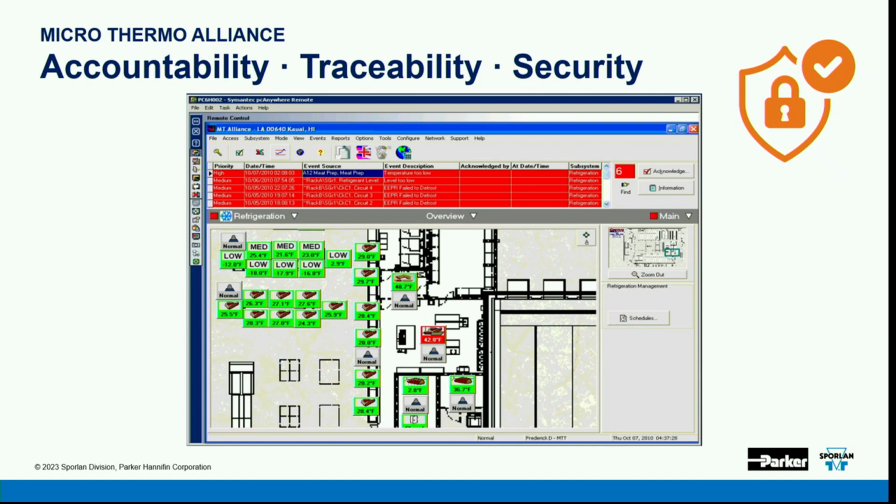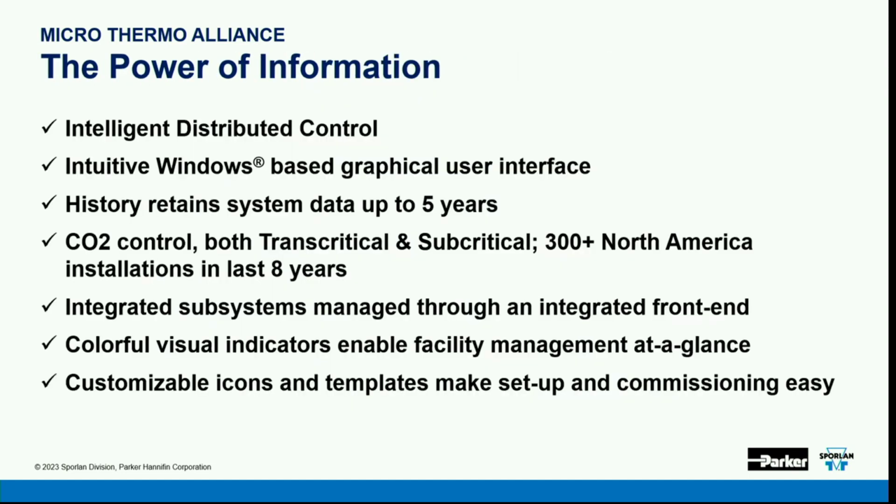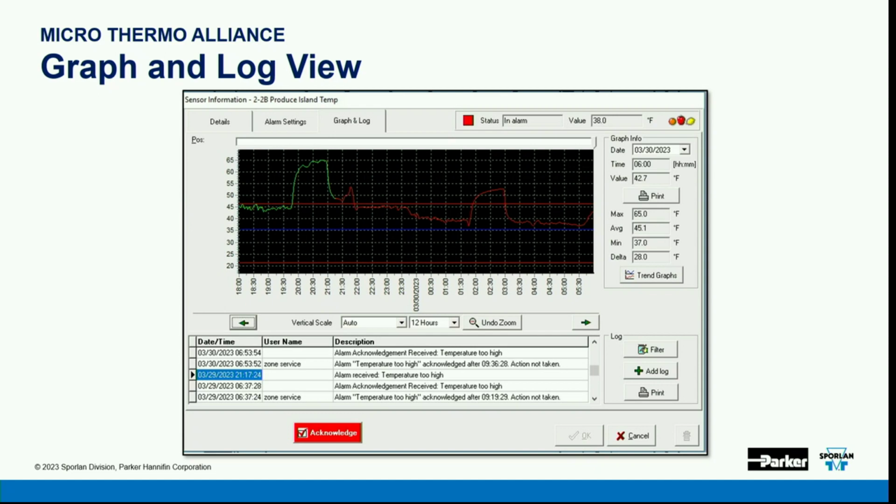So now you want to go even further, you click on it again, and you zoom directly in, it'll open what we call the process window. Now, all of our nodes have process windows. And this is just a simple temperature sensor process window. And you can see what happened: the temperature started rising. And right in this period here was long enough to trip the alarm. And then the actual graph itself goes red.